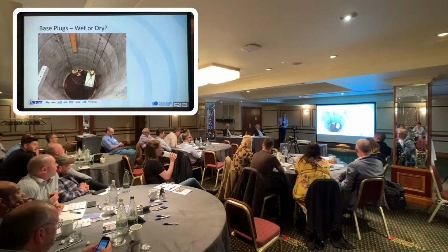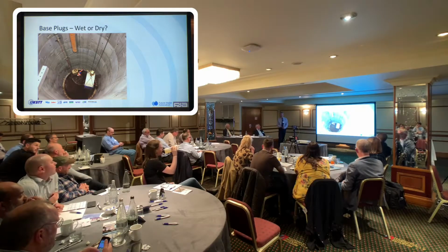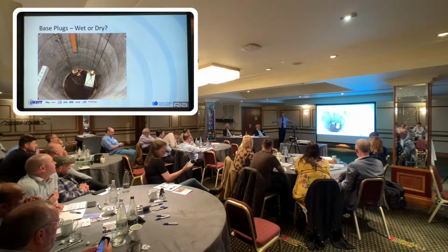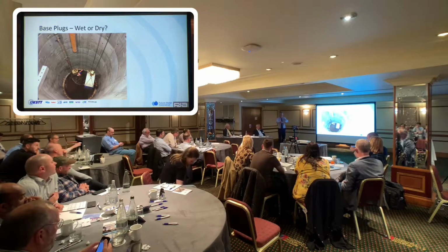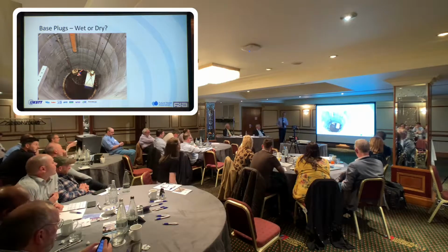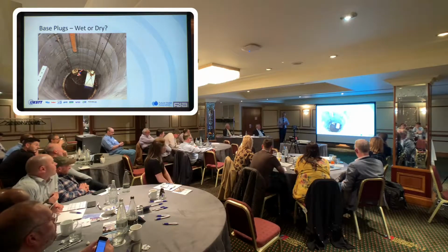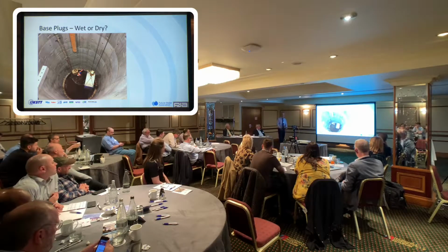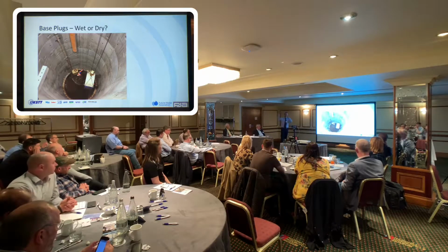Yeah, absolutely. So there was a temporary works design performed for a shaft next to a river, and the temporary works design required the collar, which is a big concrete donut, you know where the rams were in that picture. After we poured the base and before we pumped out the water, we had to dowel the collar to the shaft to mobilise that extra weight so that the thing didn't pop out of the ground. Guess what didn't happen?